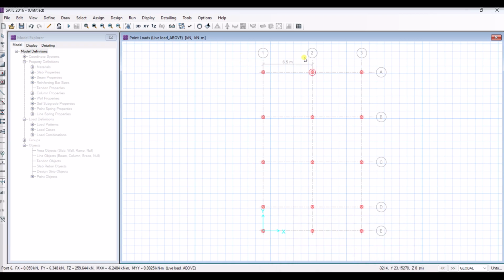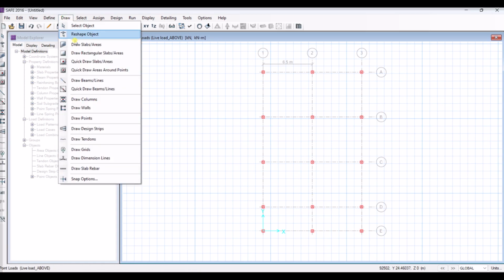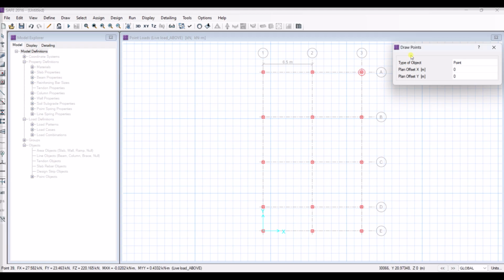Here we have another limitation when we draw our footing. Then we need to check that limitation. Okay, this is about the settlement limitations. So for making this raft footing or mat footing, I need to choose these dimensions. I will keep 1 meter of projection from these columns or load points or corners.